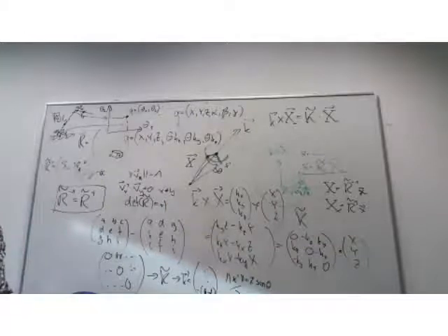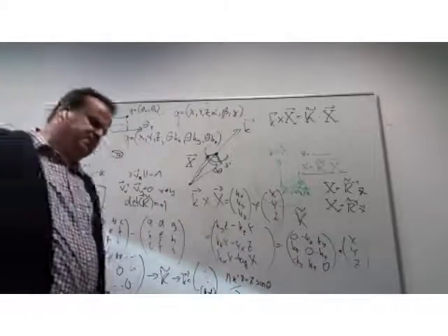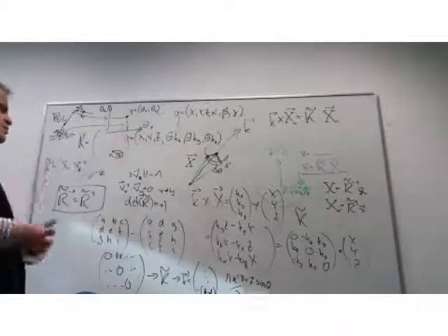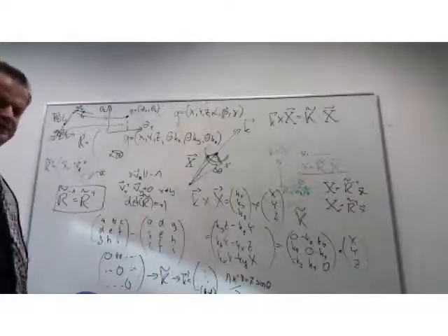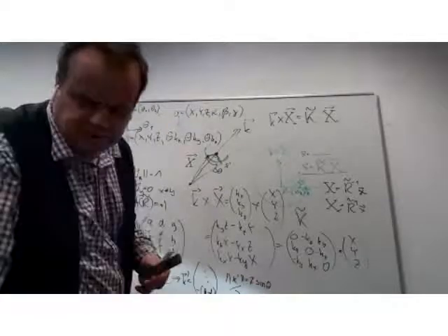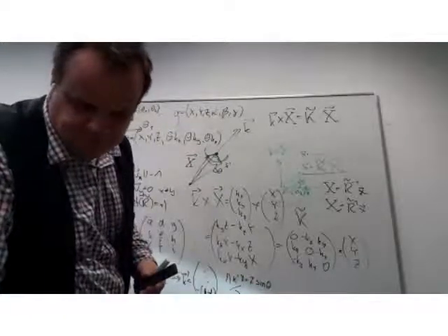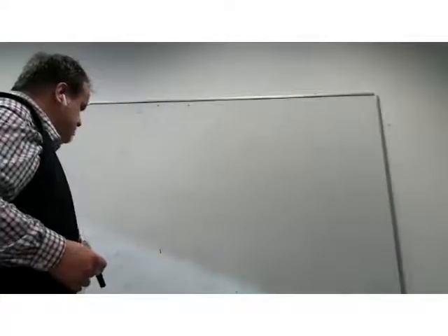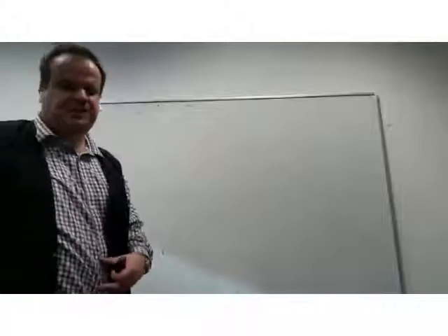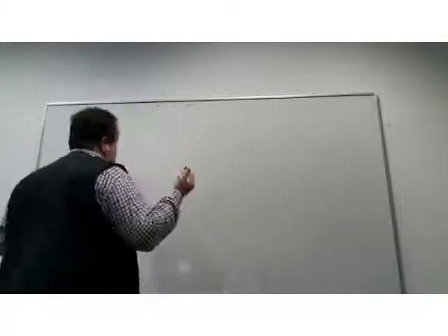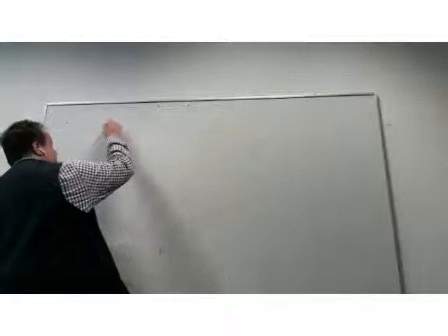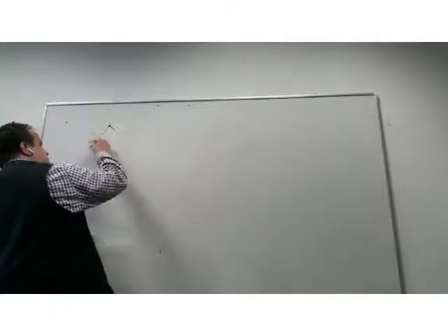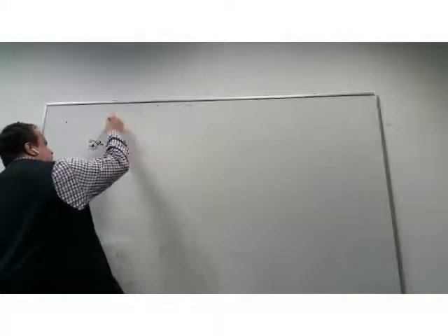So what's the dimension of the configuration space? It should be the minimum number of degrees of freedom required to represent something. Why is it the case? Let me just stop it for a second and erase the board. So why do we need to choose the minimum number of parameters describing the motion? Well, a simple reason is I take this type of manipulator with θ1 and θ2.